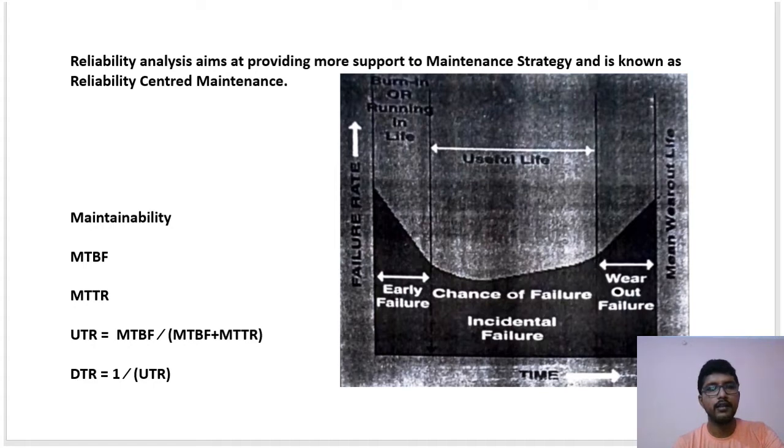And mean time between failure, it should be high. So these parameters are for reliability centered maintenance. And when you make the equipment reliable, we need to have more stress on certain aspects so that just the basic maintenance check is not enough. We need to go beyond that and ensure that it performs smoothly, normally, without any hindrance, without any flaw, without any breakdown, unexpected breakdown, undesirable breakdown, leading to outages and loss of revenue, etc.